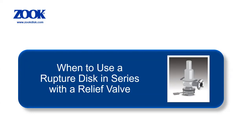However, there are also related challenges when installing a rupture disc upstream of a safety valve. Because a rupture disc is a differential pressure relief device, pressure cannot be allowed to develop in the space between the disc and the valve devices, and hence a suitable telltale indicator should be installed to ensure pressure build-up downstream of the disc is detected and eliminated. With the addition of a rupture disc in the relieving system, the flow capacity will need to be considered, and we will address them when we touch on sizing later on in the presentation.